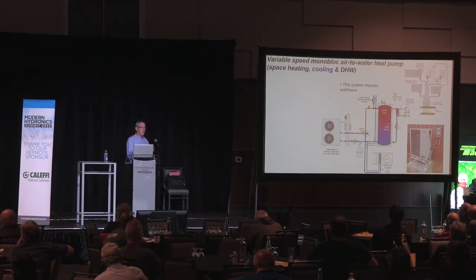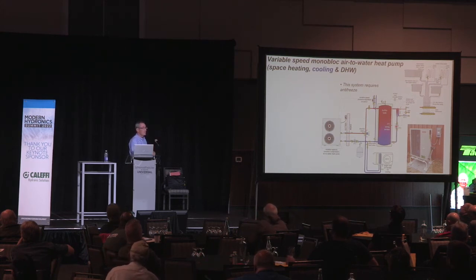But you don't want to go in there with a little 3 by 8 inch brick with 5 plates in it. It just doesn't have enough surface area. So there's online sizing software from many of the heat exchanger manufacturers that let you size that up correctly.